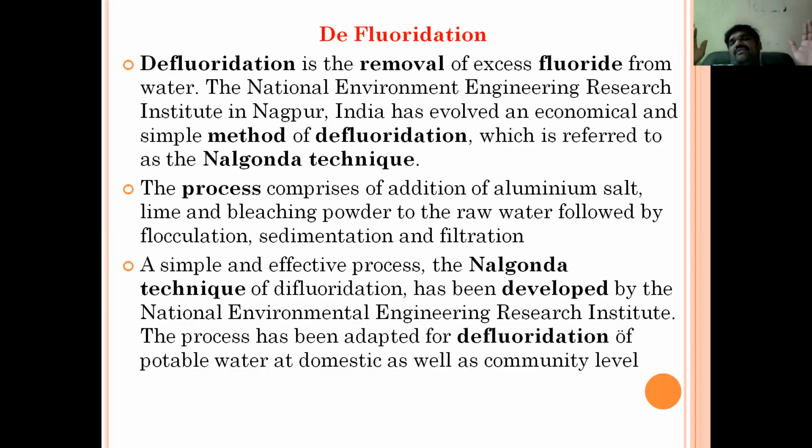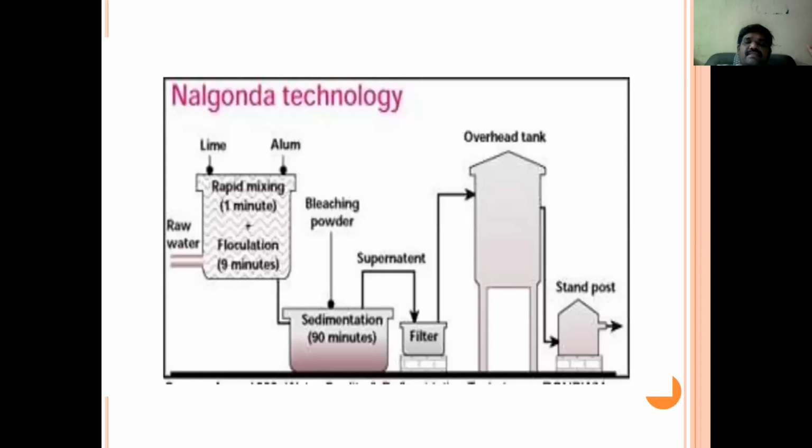There are different techniques to remove this fluoride concentration from the water. Among them, today we are going to discuss one particular, highly accepted method, that is the Nalgonda technique. It is developed by NEERI, National Environmental Engineering Research Institute, Pune, and the process is adapted for defluoridation of potable water at domestic as well as community level.